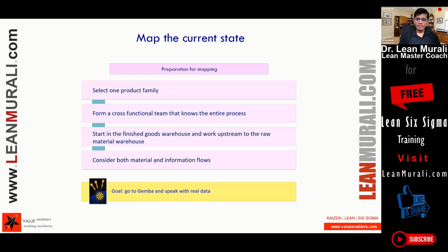We will also see, we will collect some process times, and some of the things what you have typed will definitely come. For example, changeover time, because setup times are there, which is changeover time. Cycle time, mostly we'll get. In some cases, people will capture the up times or the down times. Some quality data, also they'll say 1% rejection, 2% rejection in this process, 5% rejection in the process, things like that, and indicate it. Now, you're writing the cycle time.